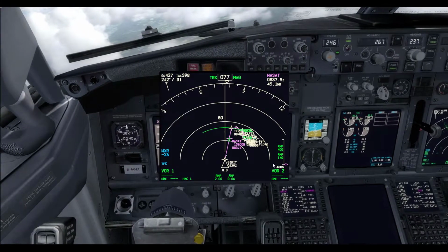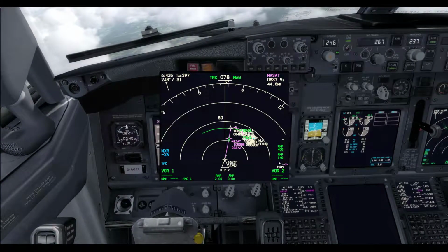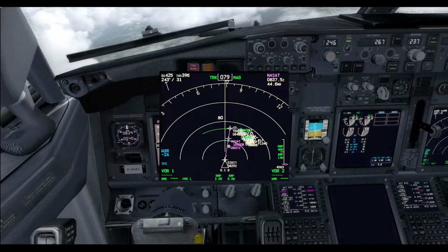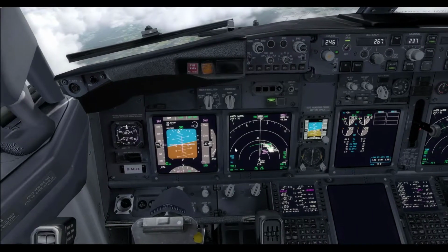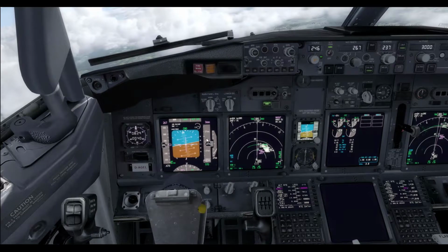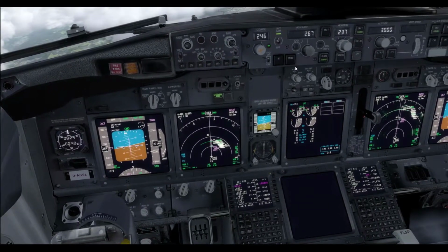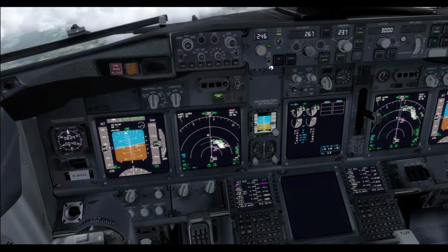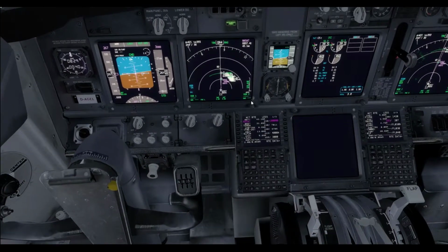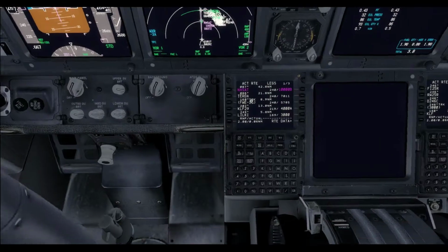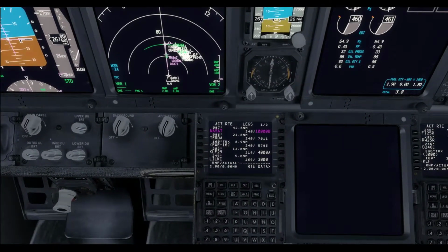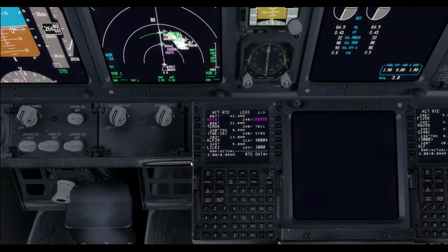I'm really hoping we can re-achieve our descent path, but I think it should be more than possible. Just remember that at flight level 100 you have to put your speed back to 250. To be on the safe side, I always put it to 240, because in case of gusts or something you always exceed 250. Fine. What else can we do?